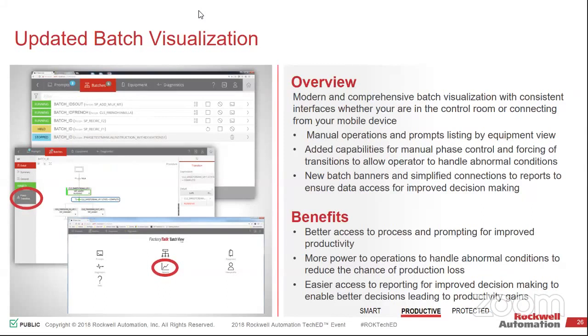He was voluntold. Yeah. So PlantPAx 4.5 utilizes batch version 13, and batch 13's been out for about 6 months, but now PlantPAx is catching up. So part of that batch release is an update to the batch visualization options you can have, and the main point of this is it doesn't replace an operator workstation; it adds to it.